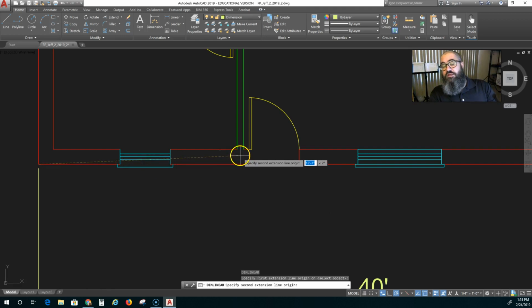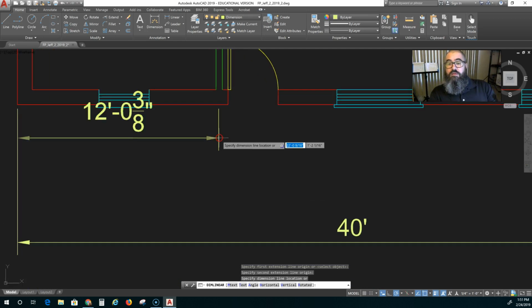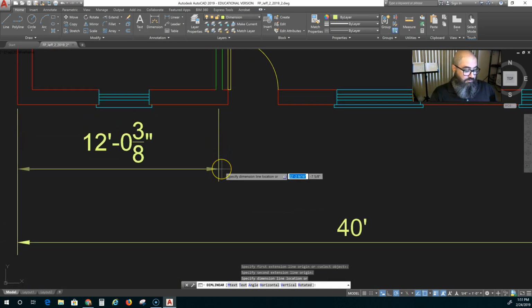Make sure you don't have any reference geometry turned on, but just kind of get it right there in the center. Okay. And pull this down and say at 0 for the x coordinate and negative, so the other one was 8 feet, so this will be 6 feet.